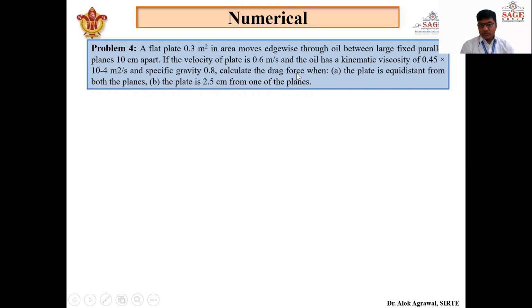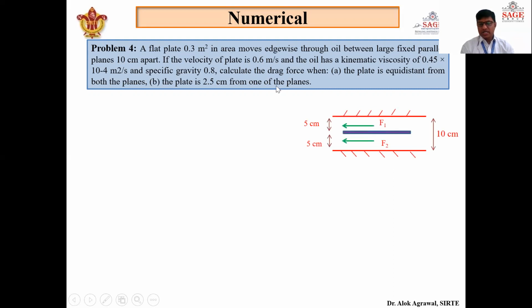Now in this problem we have to calculate the drag force in two different conditions. The first condition is when the moving plate is exactly in between the fixed parallel planes, and the second condition is when the moving plate is at a distance of 2.5 centimeter from one of the planes. So there are two different conditions, and we will see that as the position of the plate changes, the shear stress and drag force also change.